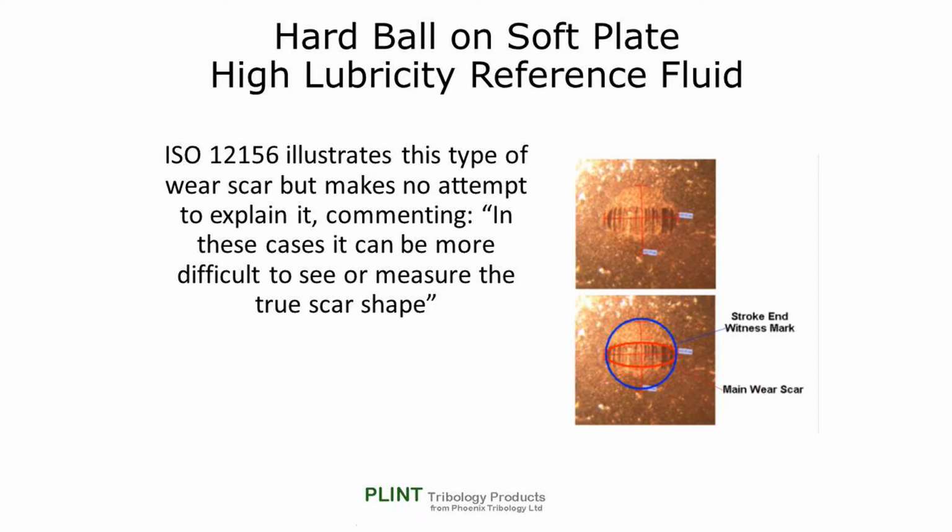Indeed, ISO 12156 both mentions and illustrates this type of wear scar, but makes no attempt to explain it, simply limiting comment to, in these cases it can be more difficult to see or measure the true scar shape.